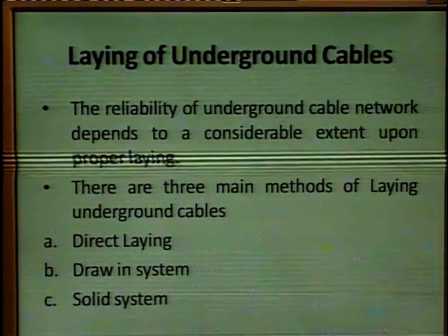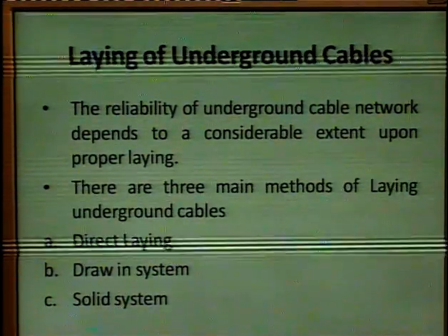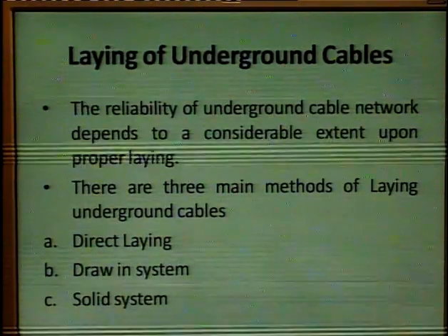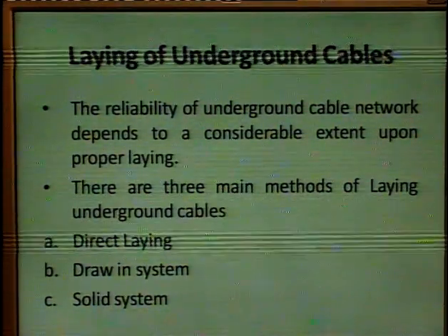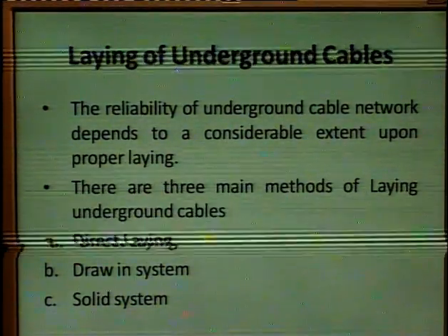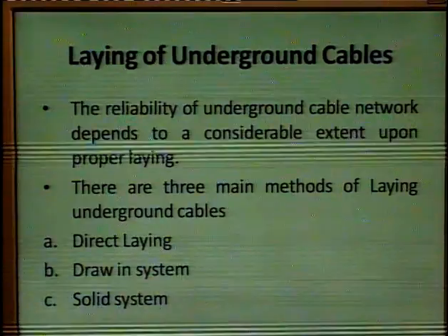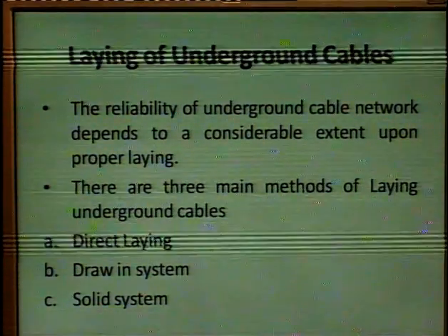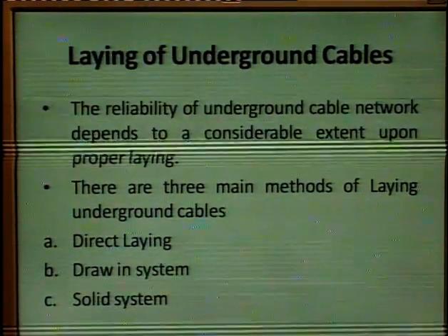First is the direct laying, then the draw-in system, and the solid system. So the three ways of cable laying are direct, draw-in, and solid system.